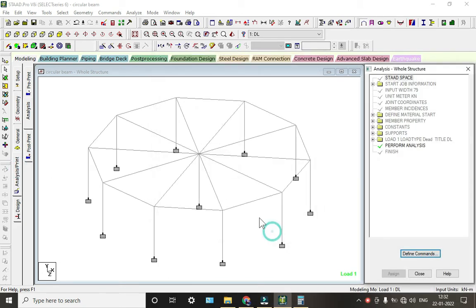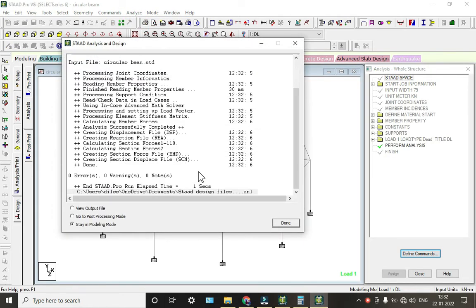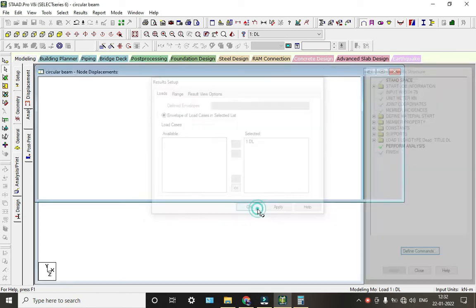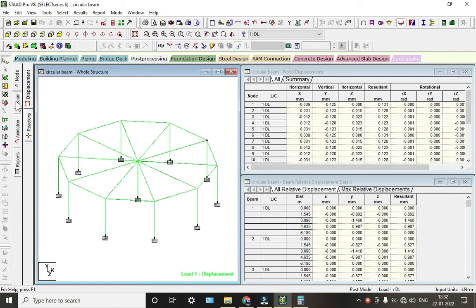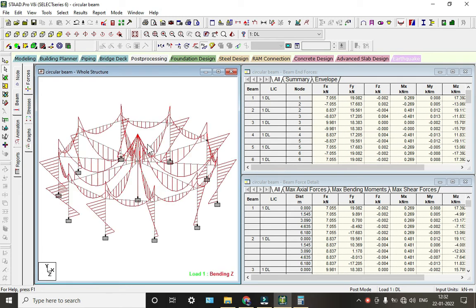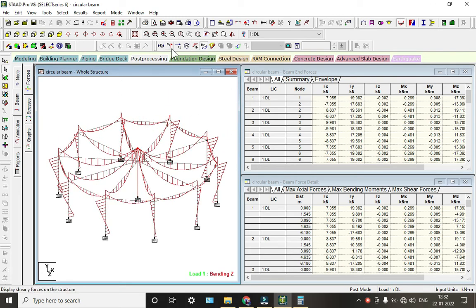Now go to this FC and we have to assign all these parameters to our structure. Click on assign and save. Click on Fy, assign to view, assign and save. Again Fy sectional, assign to view, assign and save. Maximum reinforcement, assign to view, assign and save. Design beams.